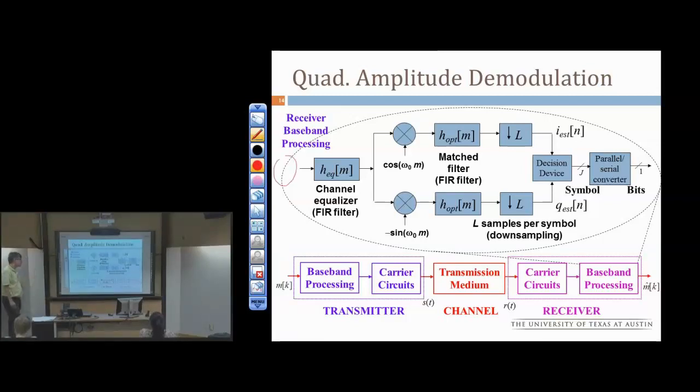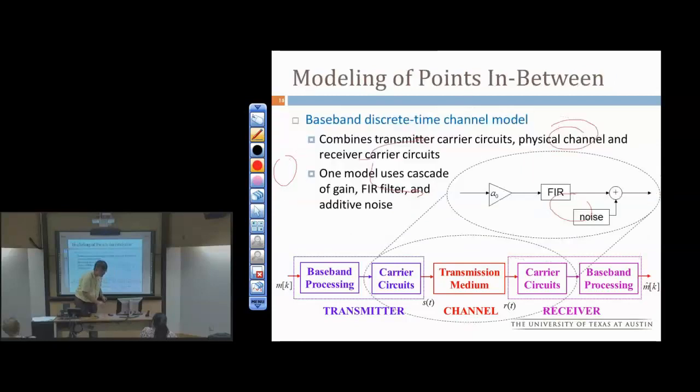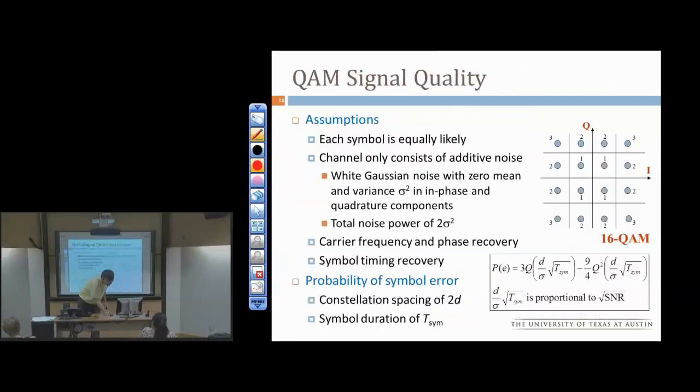And we can just include those in the carrier circuits. So demod here, we have 2 channels come in, and we simply do PAM down conversion, 2 channels of that, 1 in phase, 1 quadrature, and then finally get the 2 symbol amplitudes and look up the nearest point in the constellation map. So the rest of the block diagram simplifies very nicely.